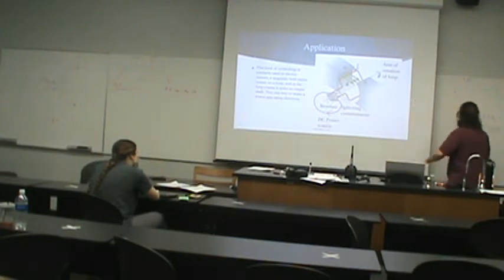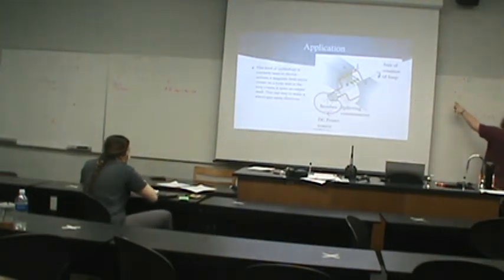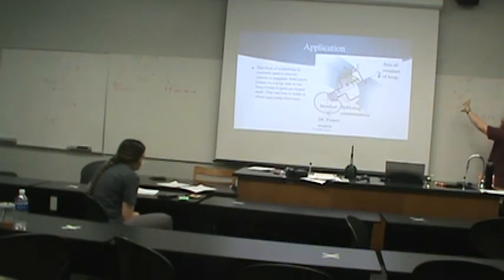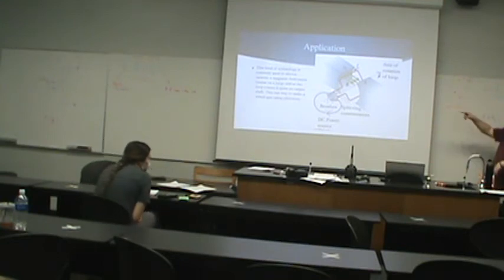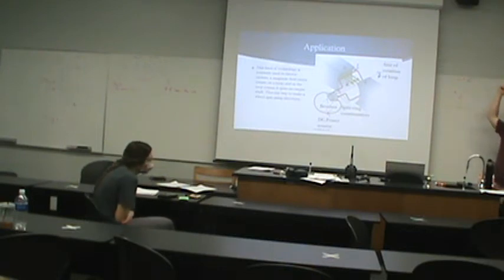Because if when the wheel gets to this point, there's no longer any current in it, there won't be any torque anymore. So the wheel's momentum will just keep carrying it through. Then, once it's gone around and is in a position to accelerate again, the current will come back on and the torque will accelerate it through another cycle. And this will be better illustrated when we build this type of motor together.